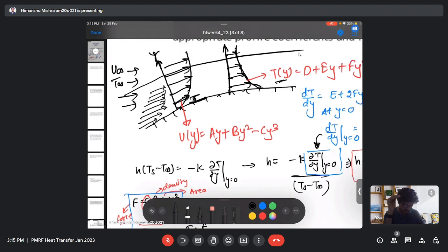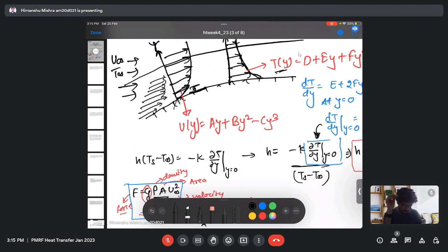Due to the shear stress, there is the velocity profile. The highest shear stress occurs at the surface of the wall, which means there is a rubbing of fluid particles over the surface, which results in a net stoppage of the fluid parcel.